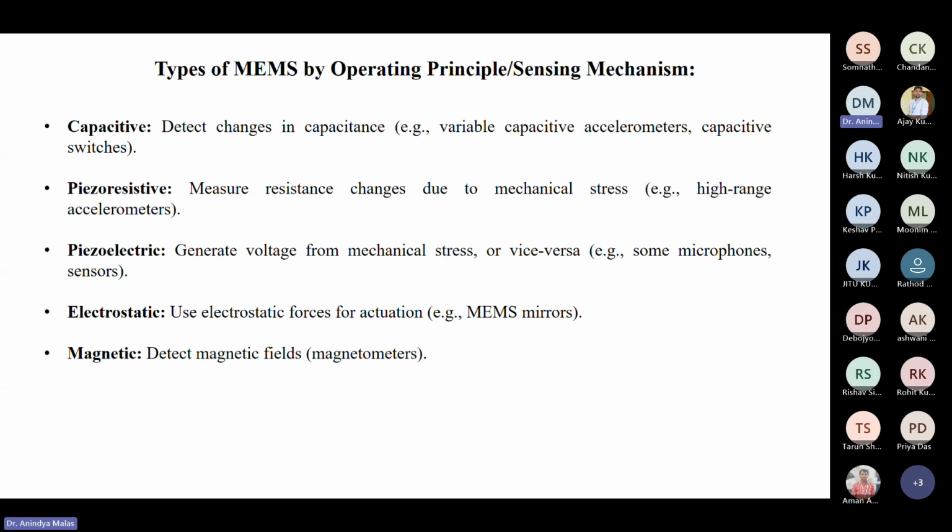So that is a type of electrostatic MEMS. It is called electrostatic MEMS, where an electric circuit and a capacitor are used. And now piezoresistive and piezoelectrics are more popular nowadays. Piezoelectrics means there are some materials that, when you apply some force on that material, actually generate some electric signal, and the change in displacement is proportional to the generation of the electrical signal.